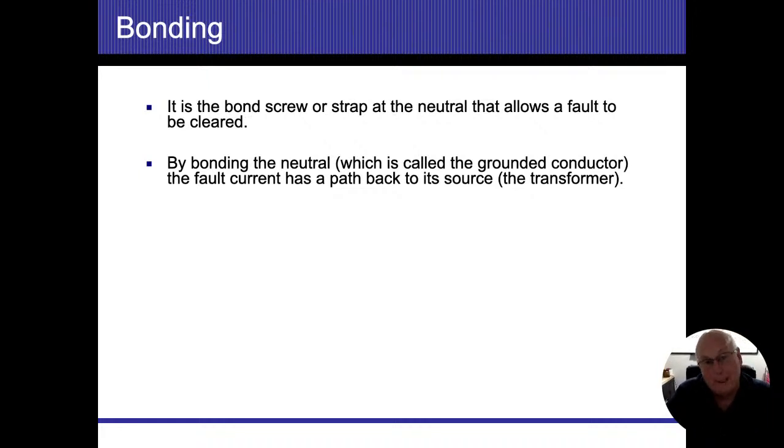When we open up our panels, the first thing that we're going to look for is the bond. I want to verify that I got my ground connection to my neutral connection. That's how I know that if there's any wires that come loose anywhere that I can't see, at least I got some sort of a pathway, maybe. That I have a pathway at that point in time to get it onto the neutral system.